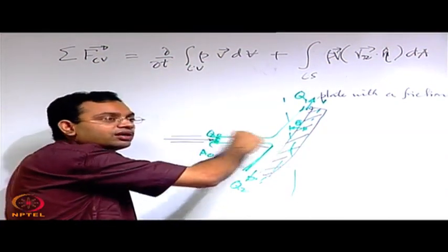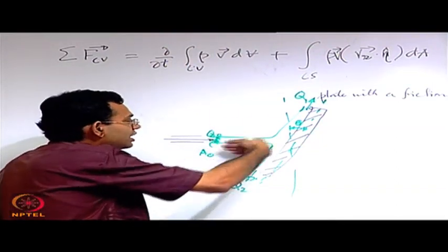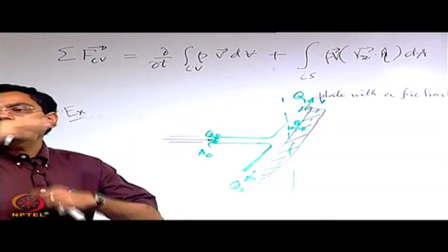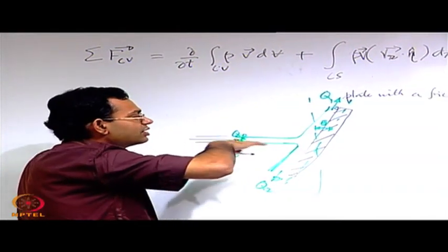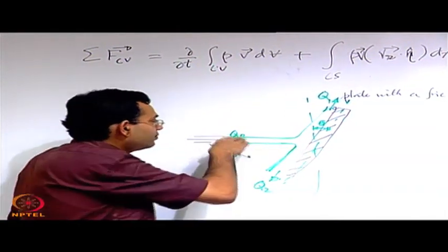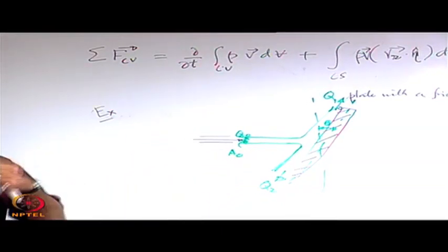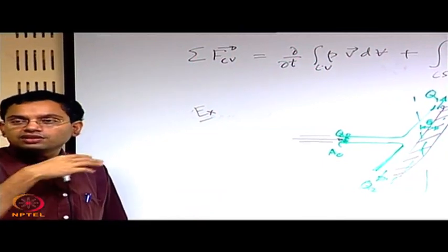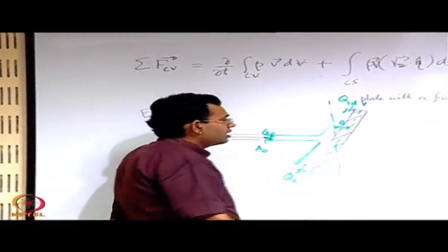This is a free water jet exposed to the atmosphere, but the water jet takes the form of a tube, its outer periphery takes the form of a tube, and the outer ones are the extreme streamlines. The figure drawn here, the lines represent the envelope of all the streamlines. So, this is called a stream tube, which engulfs all the streamlines. The same is there for the exit ones.